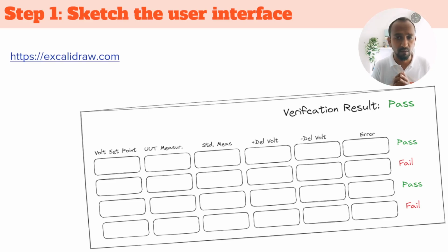For example, for a 1 volt set point, after all the resistance on the wires that connect the instruments, I might actually be getting from the power supply 1.0001, some 0.1 millivolt extra on it.